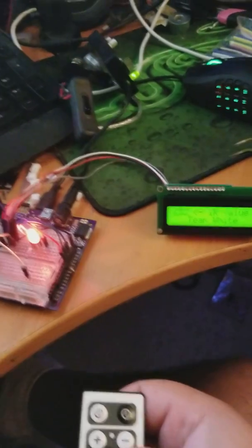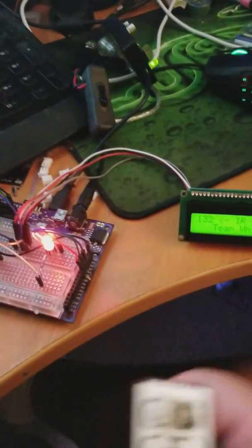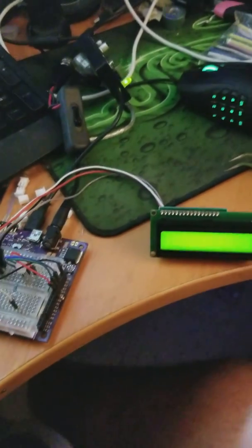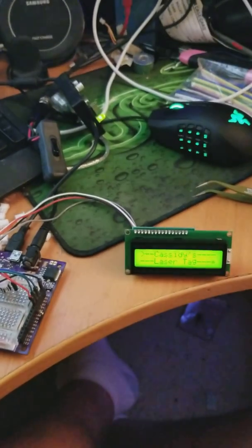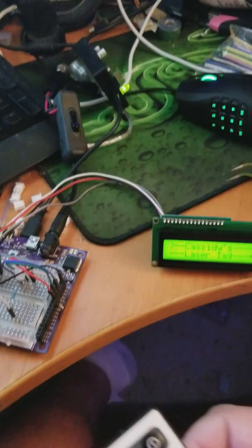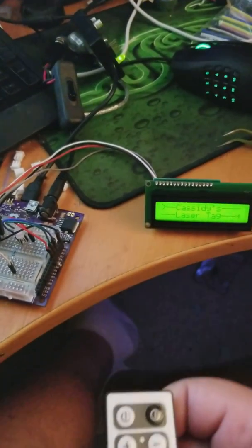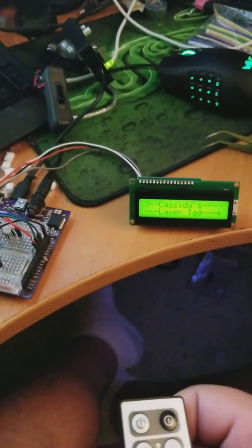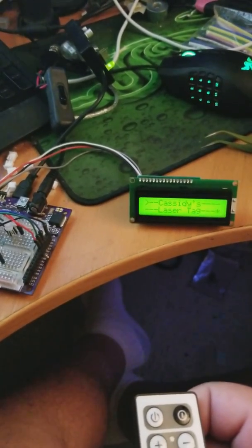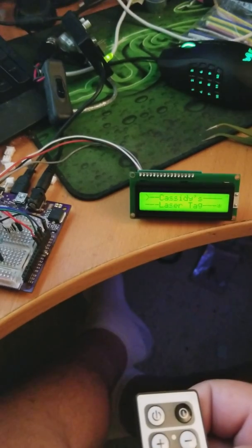Uh-oh. Is it white? No, it's red. Why is it red? So now we got to debug something. It's probably overloading the chip, because the chip's not designed to handle that much current for a white LED. So each channel, when you turn on 3 things, each diode is drawing 20 milliamps.